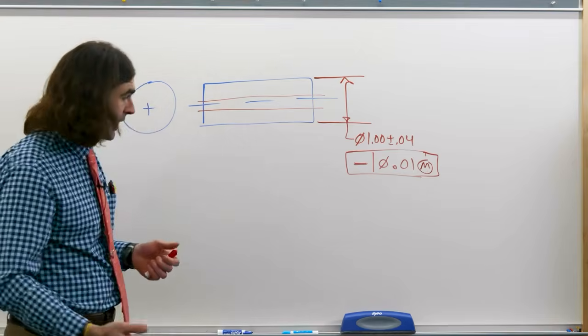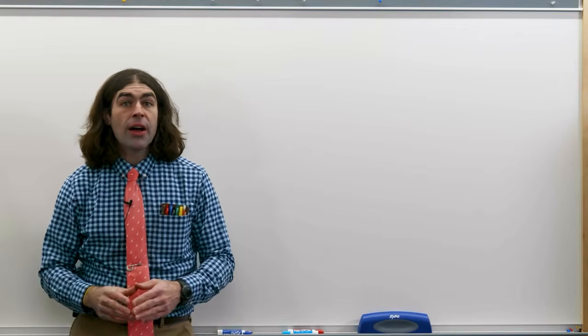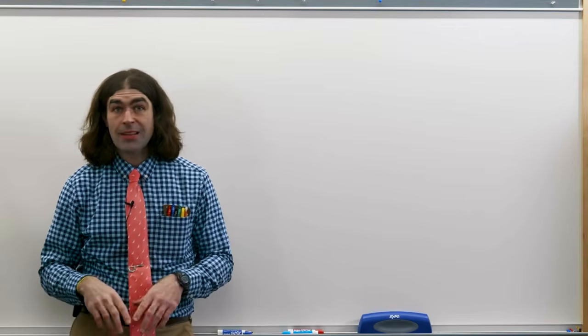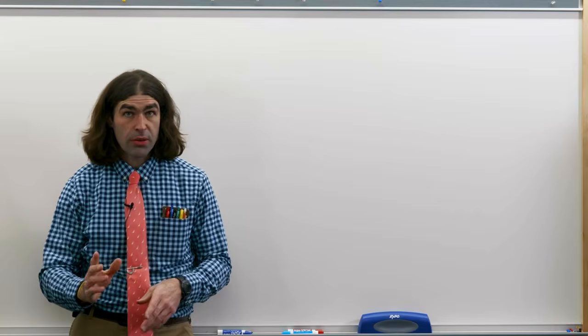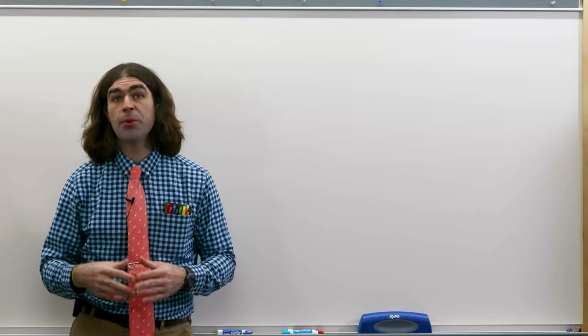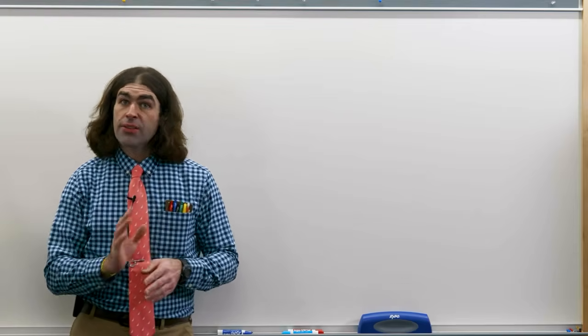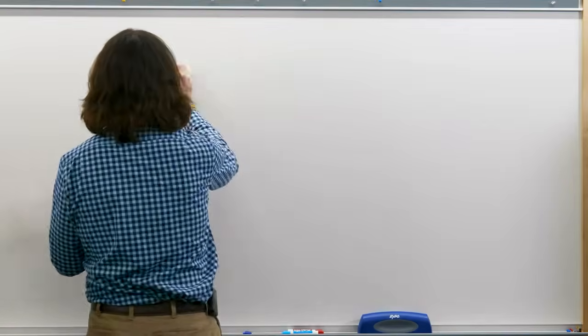So let's look at flatness. Just like straightness, it applies in two very different ways. It can apply to the surface of a plane, or it can apply to a derived median plane. Luckily, it works a lot like straightness. Let me give you an example.